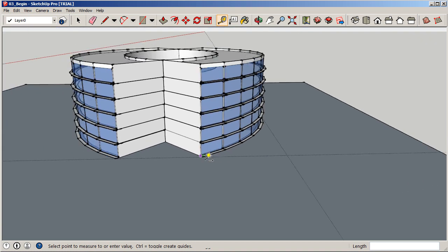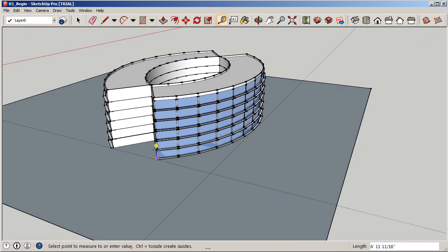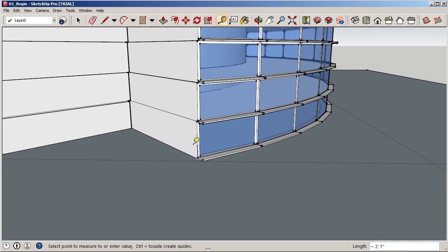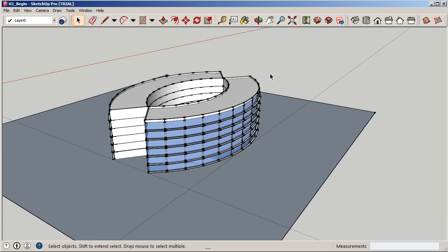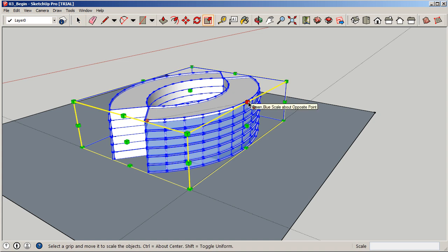All right. So by us scaling the way we did, it's going to affect our level to level height. So right now it's at 8 feet. So let's do an additional scale here. I want to increase the height on this a little bit. So we'll go ahead and hit that, type in S, and we can grab from this middle one, and let's increase this up to a point where we want to make sure we have 12 feet headroom height.